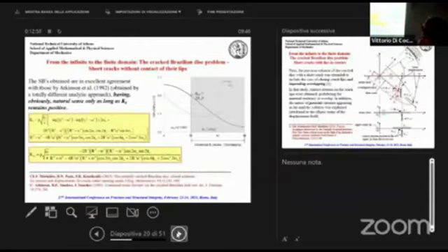Now you can see here the predictions for the stress intensity factor. Remember that we adopted the mathematical crack concept. So there is a stress intensity factor. Obviously, it is reasonable and it has natural meaning as long as the geometry does not lead to negative stress intensity factor, mode 1. So this solution was very close to the result by Atkinson, 1982.